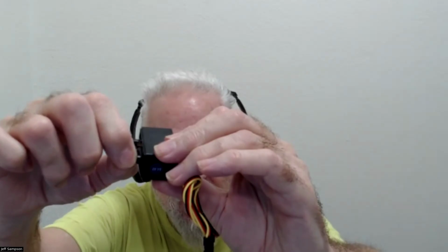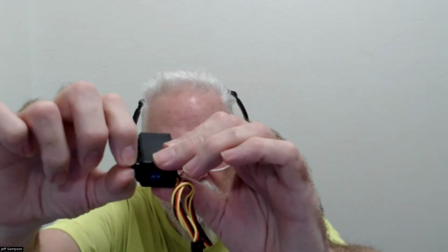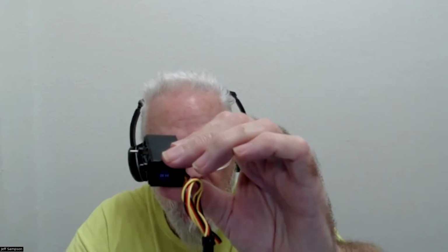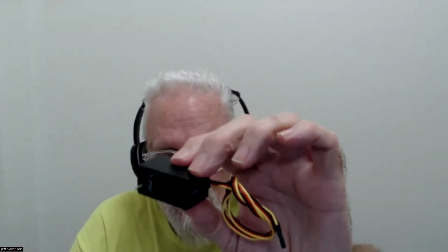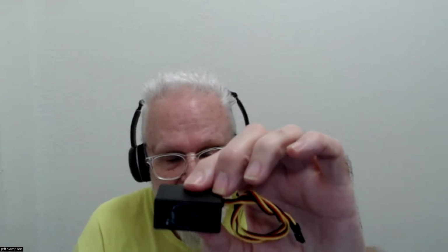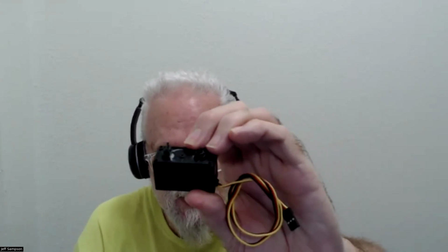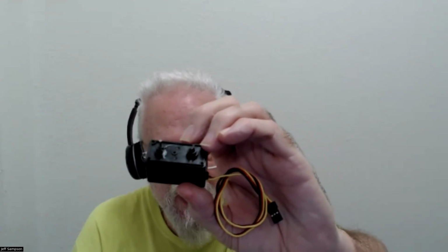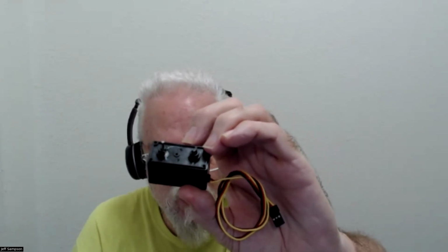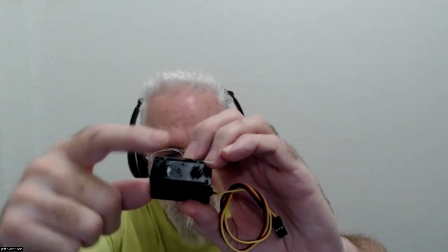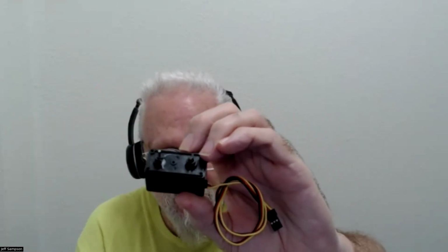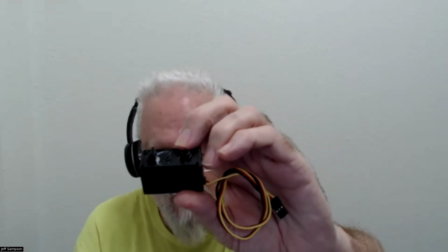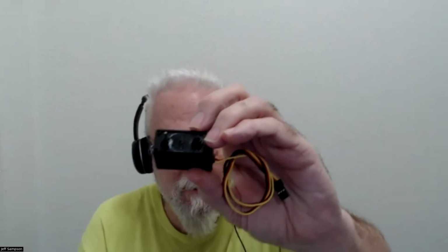So anyway, you grab that and you turn it. You turn it one direction, the motor is going to go faster. You turn the other way, it's going to slow down. When you get right to the center, the motor should come to a stop. And at that point, that's how much calibration you have to do. From then on, it should work just like a radio control speed controller. And if everything's working right, you could put a blob of hot glue on that, so the thing doesn't turn on you, and you don't bump it and have it wildly driving around.